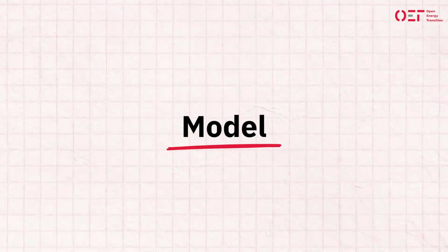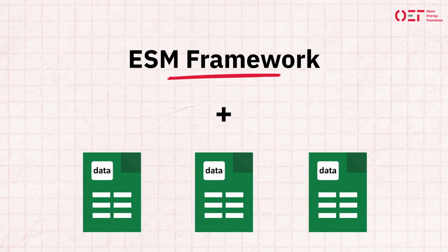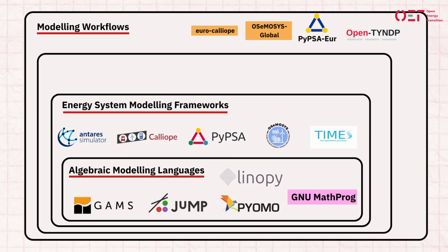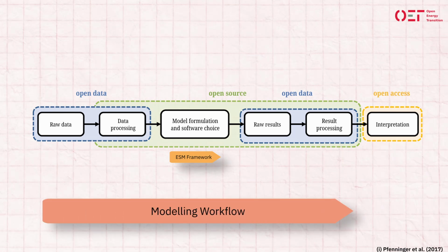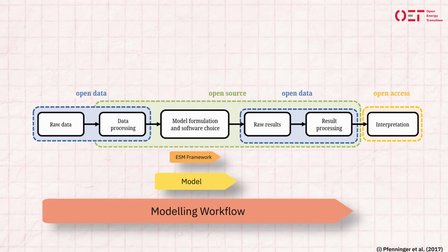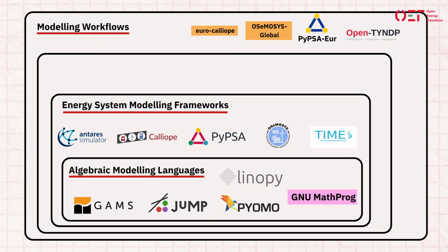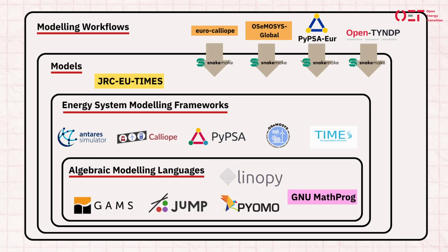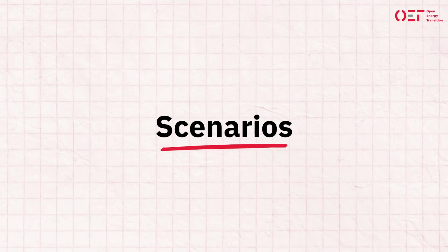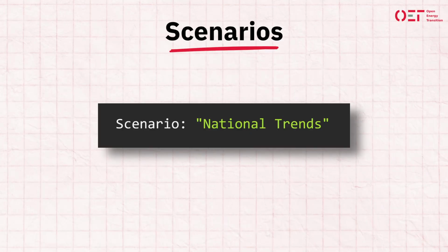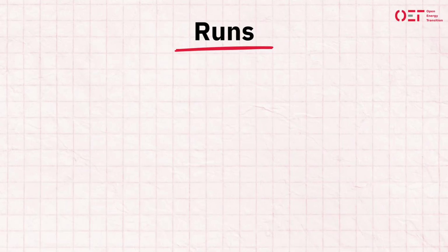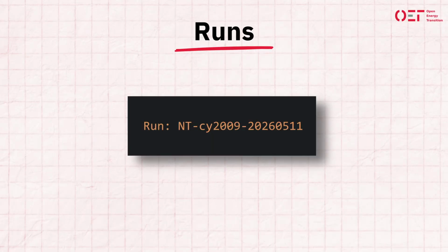To actually build a model of the specific question you want to answer, you then need to populate the framework's building blocks with data and connect them together, which is what a modeling workflow does. A modeling workflow is the process that connects raw data with results. It creates the model, runs it to produce results, and processes the results. So, PyPSA-Eur and Open-TYNDP are modeling workflows that create instantiated models, not to be confused with scenarios or runs, scenarios being a coherent set of assumptions applied to a model, and runs being single solves or executions of a model.